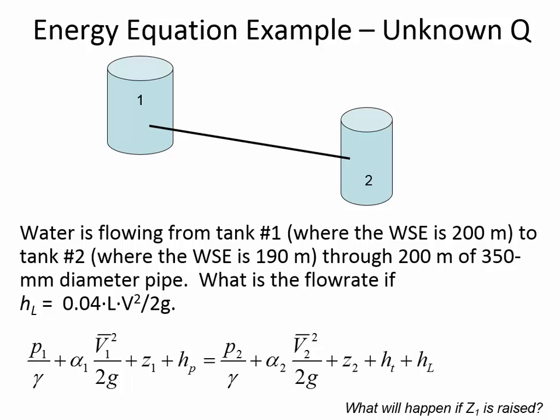Good question. So let's say that you're trying to pump water from a water tank and it's going into a mercury tank. In a situation like that, it's possible that you could have more pressure here than there. So the flow could go that direction because this delta H for a really dense fluid could have a higher pressure at the opening of the pipe than this delta H of water. In this formula, in this situation, you only have C1 minus C2.